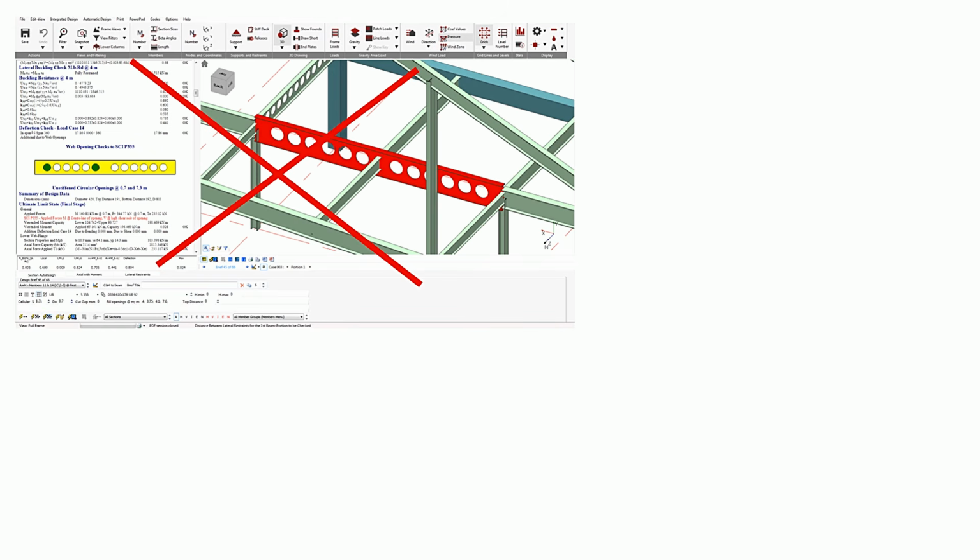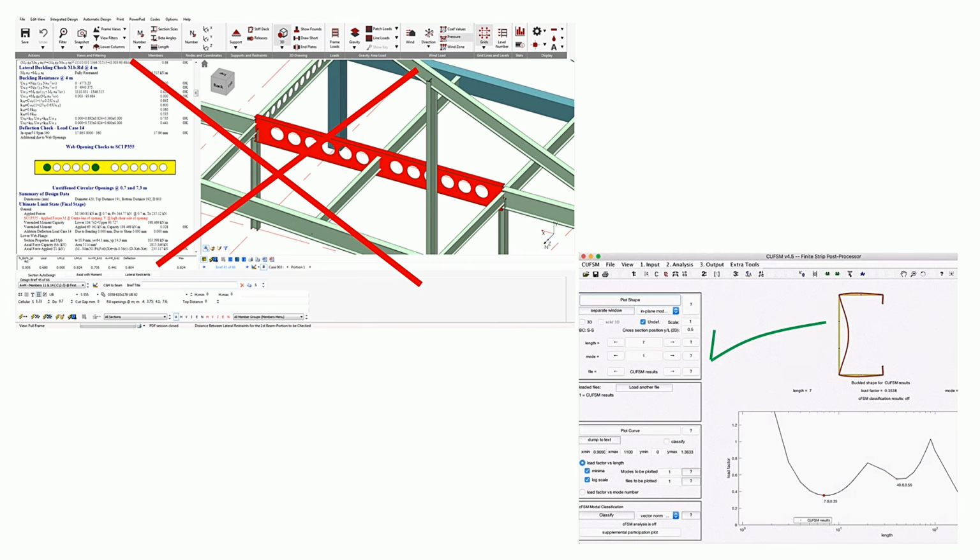AISI commentary warns that ordinary beam elements in standard structural software often do not capture local buckling, distortional buckling, or even proper warping torsion. That means they can be misleading for DSM if you try to use them naively for buckling extraction. The commentary recommends proper plate-based numerical methods when practical, and even mentions tools like finite strip analysis and CFSM in the broader system design commentary.